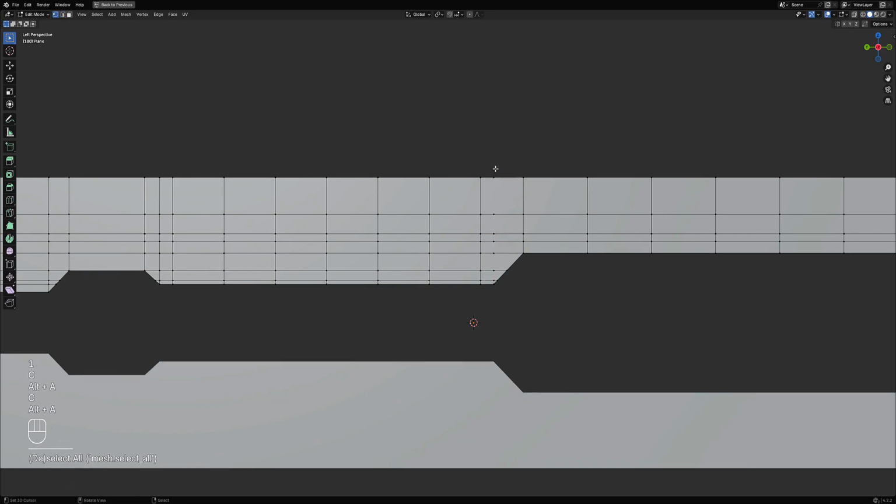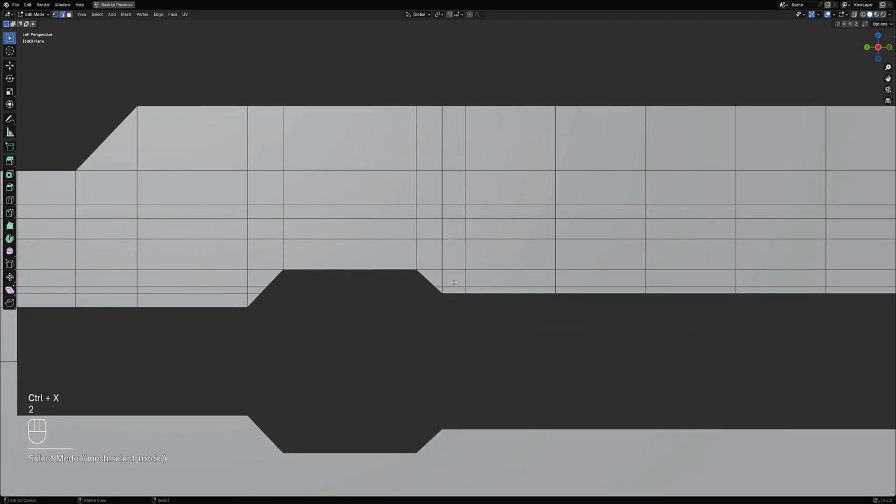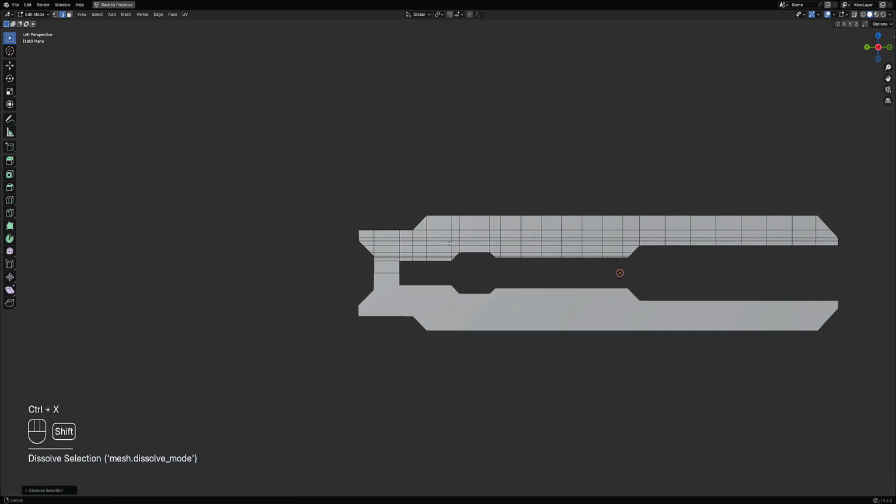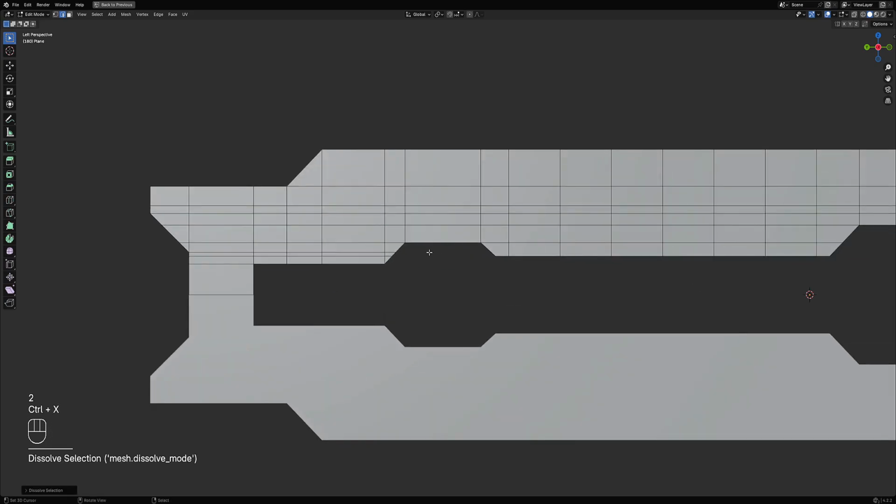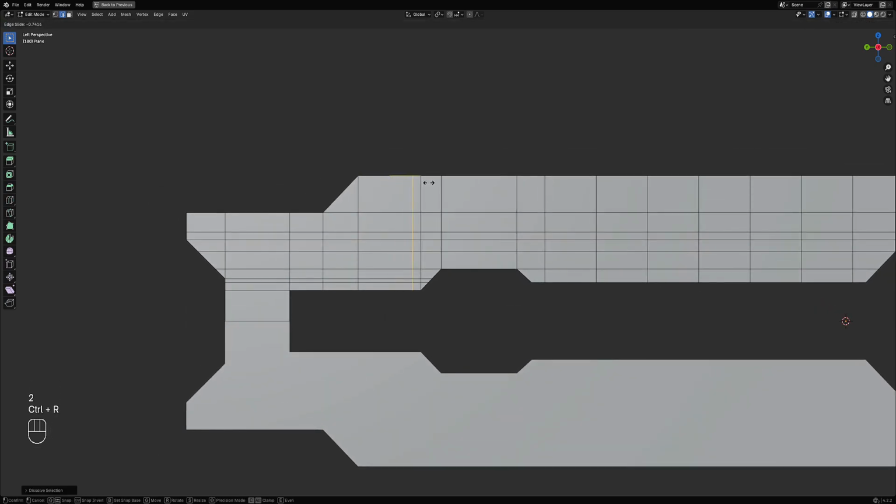But this is the only annoying thing about this delete edges. So what I do for this situation, just delete this first, and then disable dissolve, and then delete the rest. Modify this, delete this. Oops. F9, disable dissolve verts. Add one here.